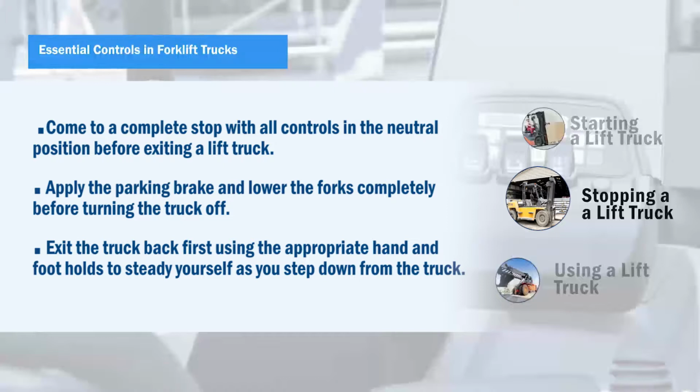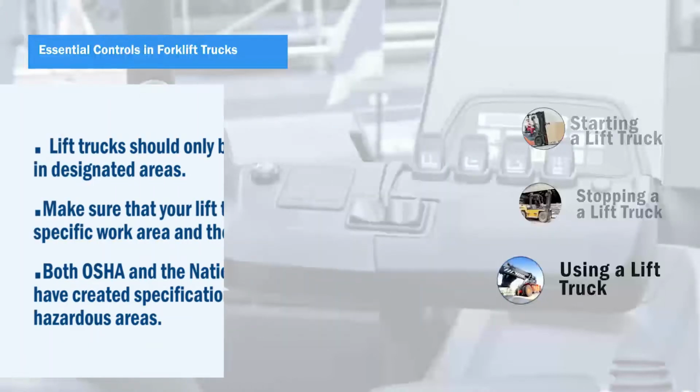Come to a complete stop with all controls in the neutral position before exiting a lift truck. Apply the parking brake and lower the forks completely before turning the truck off. Exit the truck back first using the appropriate hand and foot holds to steady yourself as you step down from the truck. Using a lift truck.